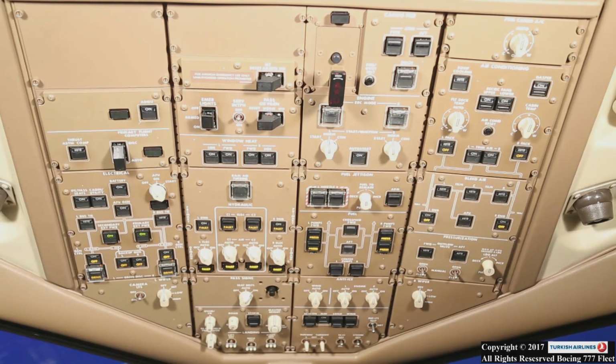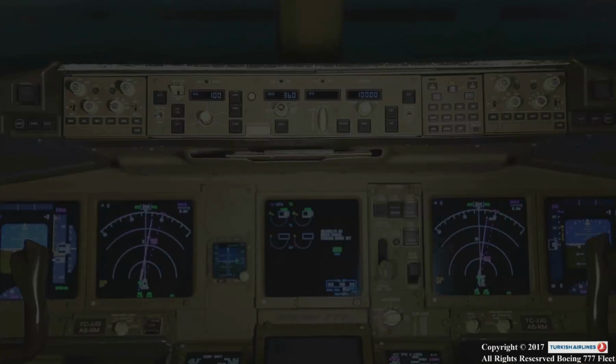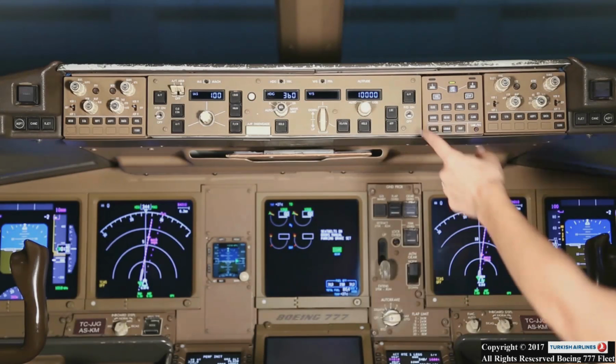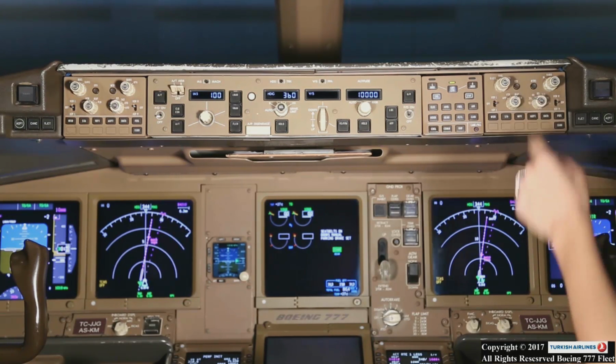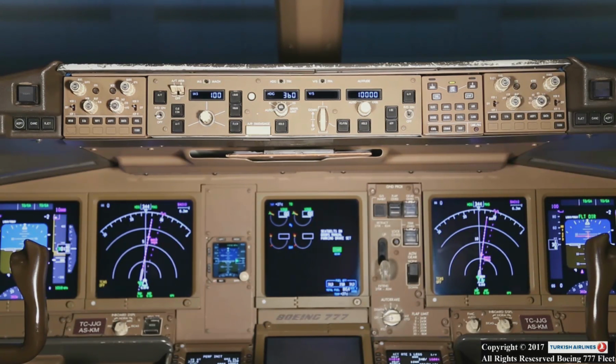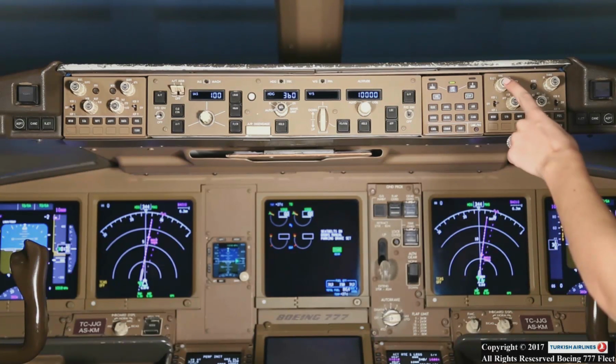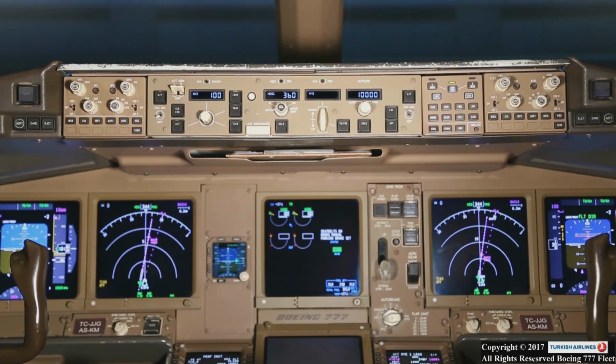Right wiper selector, off. Flight director switch, on. Display select panel, set. Lower center display switch, push. EFIS control panel, set. Minimum reference selector, radio or baro. Minimums selector, minimums shall be blank. True path vector switch, shall be blank.